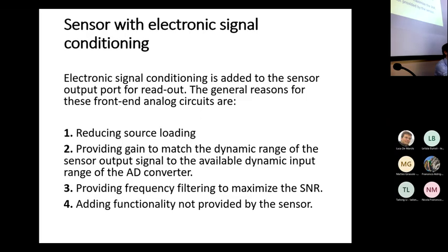Because typically noise, as we have seen, is white. Apart from flicker noise, thermal noise, which is typically the most relevant component, is white, flat in the power spectral density. So to maximize the signal-to-noise ratio, we can apply some bandpass filtering centered around the spectral content of the signal.